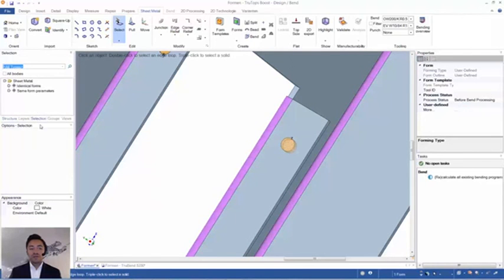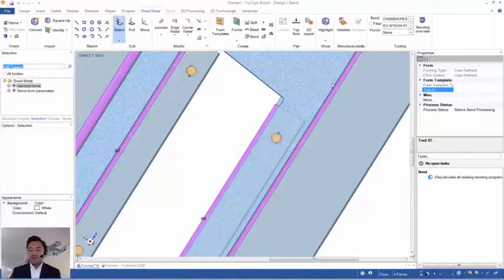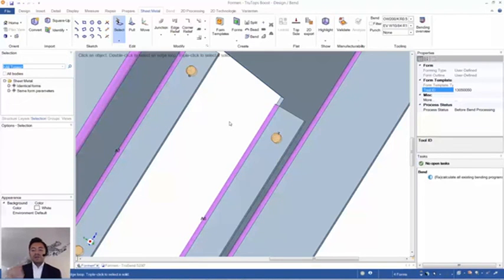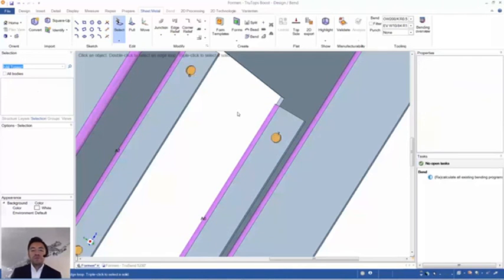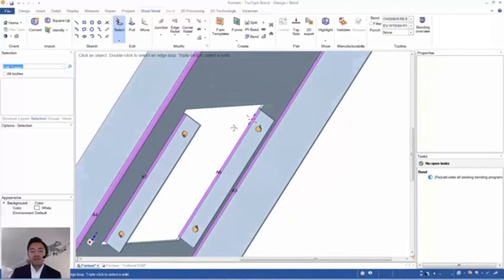If I go to my selection and look for all identical forms, there are 4 forms. You see it here at the bottom. And if you know the tool ID by heart, so it would be 130, 550 for center bosses, and click enter. The tool ID is assigned now to your forms, and within the punching module, exactly that tool will be selected for the processing.